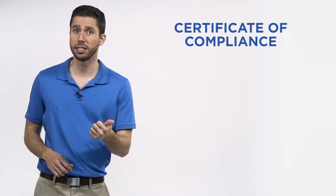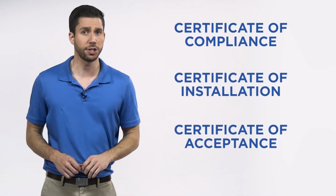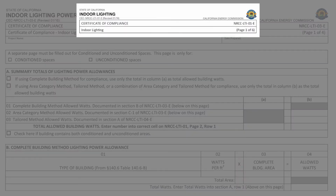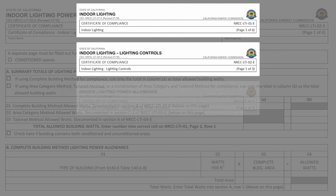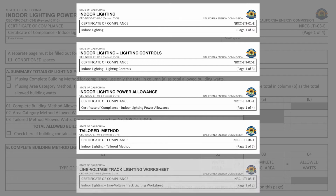There are three types of forms that are needed: the Certificate of Compliance, the Certificate of Installation, and the Certificate of Acceptance. First, let's look at what's needed for the Certificates of Compliance. The design team and responsible person are required to identify all required equipment and systems necessary to meet Title 24. They also need to identify systems that require acceptance tests. The certificate must be completed prior to applying for a building permit. It also must be incorporated into the building design plans prior to submission to the authority granting the building permit.